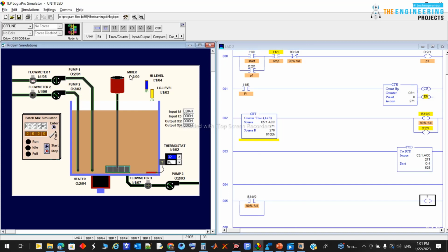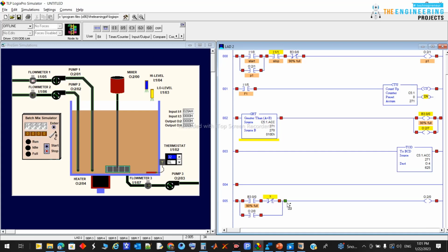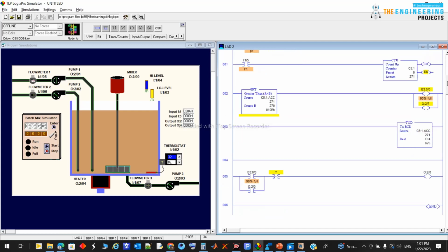So dragging this mixer here, and also I need to add one latch here from this mixer, but the mixer will run for one condition and then it will stop. So this is the stop condition for the mixer. You can go down a little bit. Okay, so this is the stop condition, and the stop condition we've been told is it will run for 8 seconds.